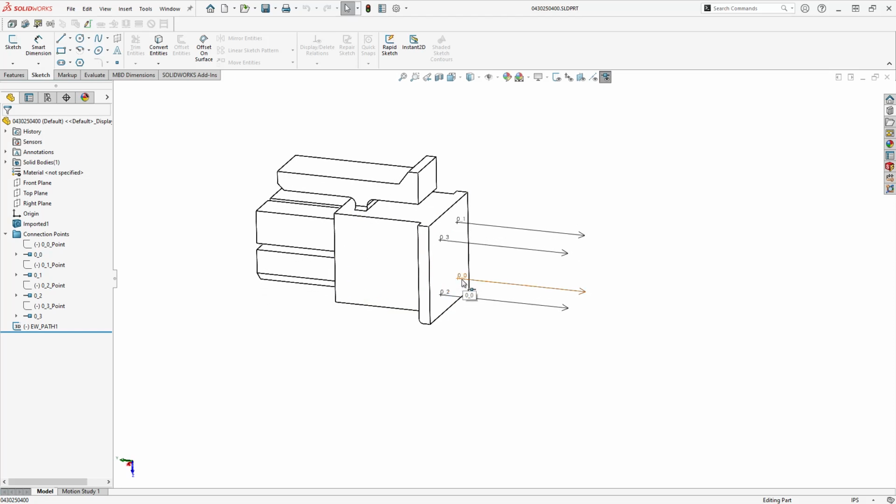So these connection points, you could probably put in a little closer. It all depends on how small your device is and how detailed you absolutely need to be. In reality, a lot of folks will just do this and then adjust their report later on to include an extra 5% or something like that for every wire. They'll just manipulate the length that you capture on the back end later on. But maybe it's good practice for you to take that connection point and put it somewhere inside of the part. That way, when the wire does come into this, it's going to stop at that connection point inside like it normally would in the real world, right?